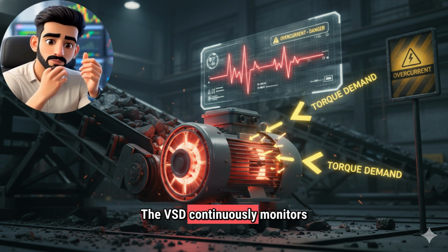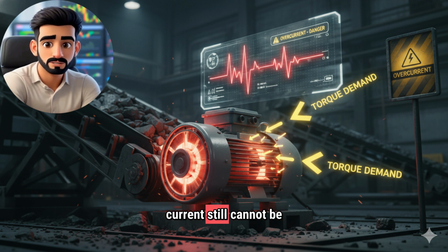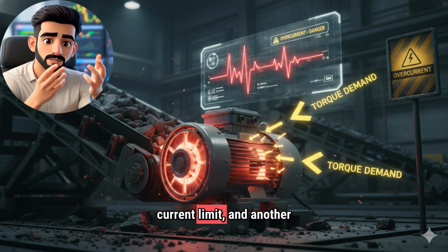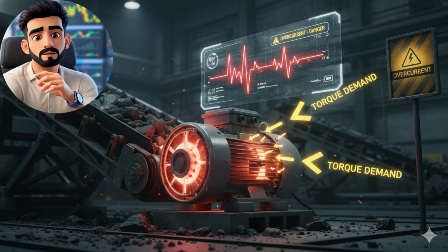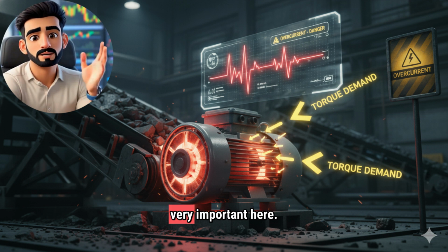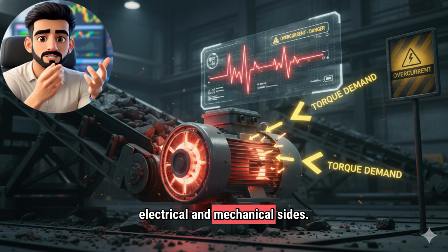The VSD continuously monitors the current. If the current exceeds a certain threshold, the drive first applies a limit, and if the current still cannot be controlled, it trips. In this setting, there is a parameter called current limit, and another parameter that determines how long the drive will tolerate an overload situation. If you set the current limit too high, the motor may overload. If you set it too low, the drive will trip unnecessarily. Therefore, engineering judgment is very important here. If I'm asked in an interview what I would check in case of an overcurrent fault, I would need to consider both the electrical and mechanical sides.